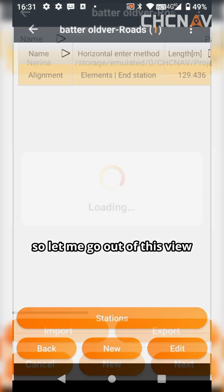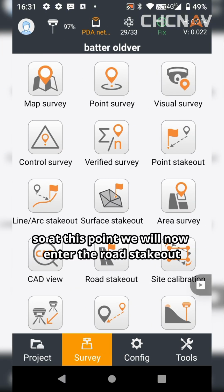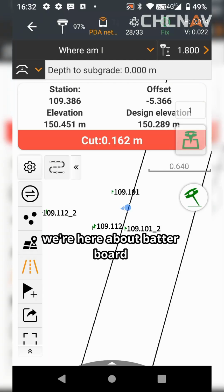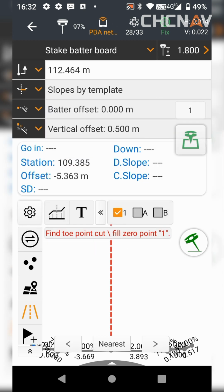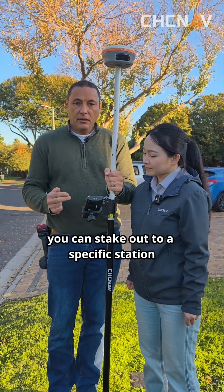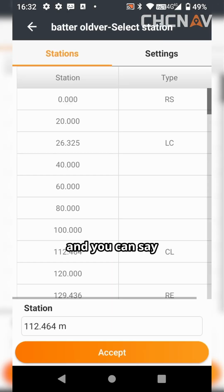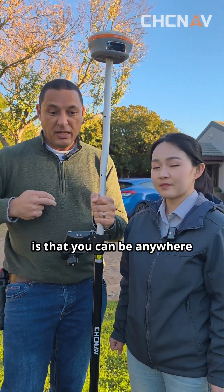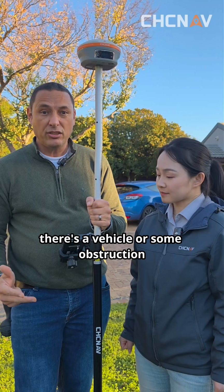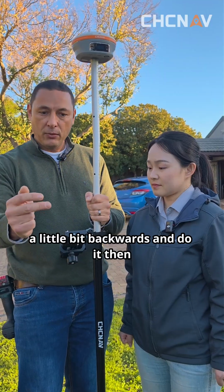So let me go out of this view and back out to the main view and go to survey. So at this point we will now enter the road stakeout. Okay, so Rachel, we're here about batter board. So let's go to where am I and just change this to stake batter board. Okay, first of all, you can stake out to a specific station. So you can pick your station and you can say I want to go to whatever station you want. But what I like particularly is that you can be anywhere, because sometimes there's a vehicle or some obstruction right there where you need to put your stake and you cannot put it there. But we can go a little bit forward, a little bit backwards and do it then.